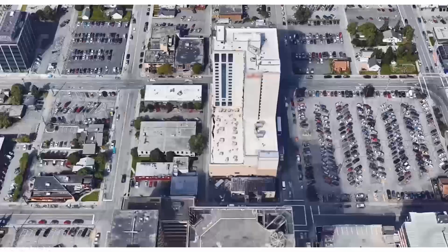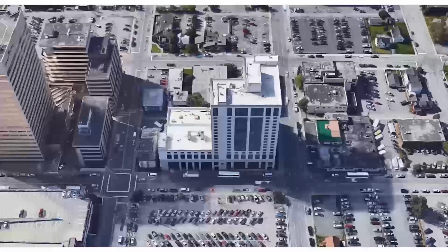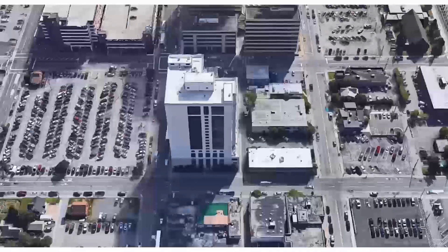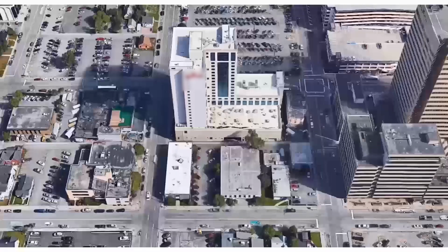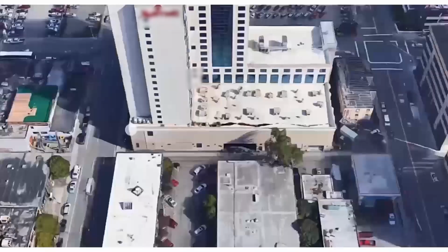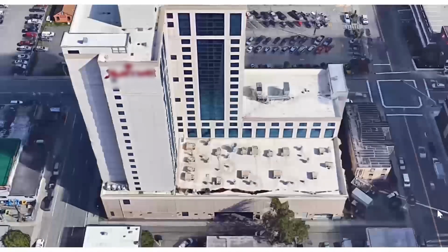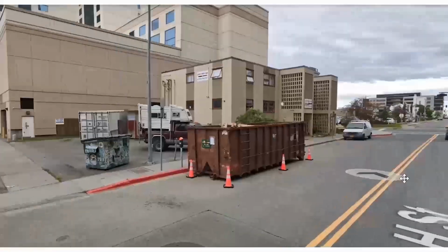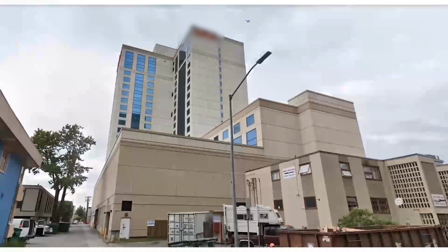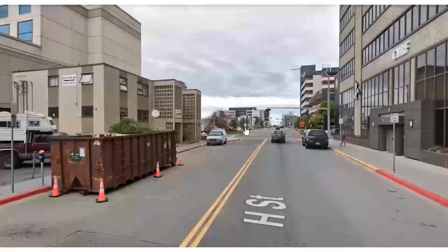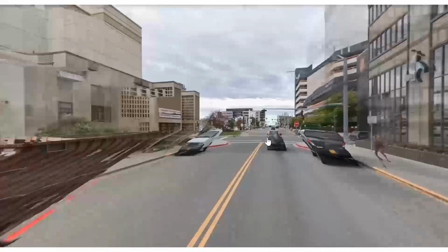All right. It's got a lot of stories, definitely more than 10. And it looks like there's a low roof, a couple of low roofs. I see some corners on the interior of the building, some re-entrant corners that might be a plan irregularity.